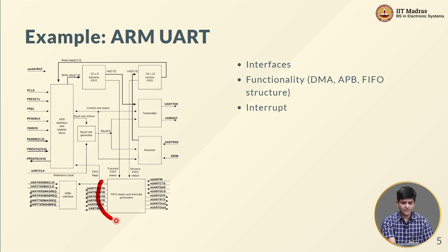There is also another block out here which takes care of the FIFO, a kind of buffer that allows you to, let us say you want to write data out of the UART, rather than waiting for each individual byte to be sent out, you can just fill in a set of values in a FIFO buffer, first in first out buffer, and the hardware internally will take care of serializing it, picking it out one byte at a time and actually sending it out, and it will take care of all the handshaking and other things that are required to send it.